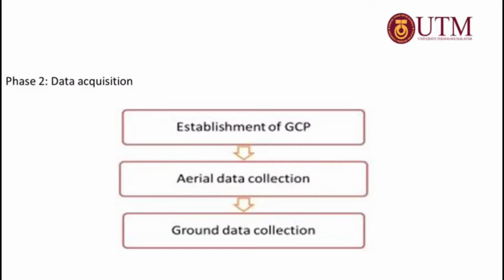In this research, GCP is determined prior to the UAV and GLS data collection because the coordinates obtained will be used in GLS data collection. All coordinates will be in WGS84 system. The GCP was set up on a point plan prior to the GPS observation. About 6 points were established for laser scanner points, meanwhile about 5 points established for UAV's GCPs.